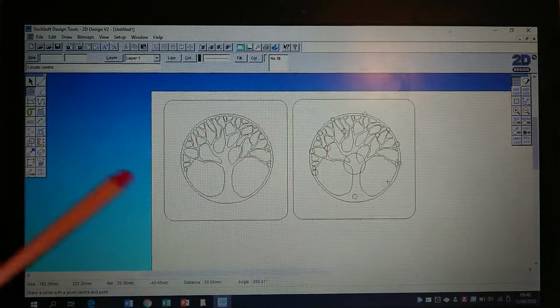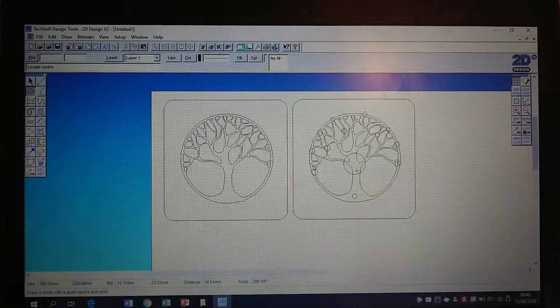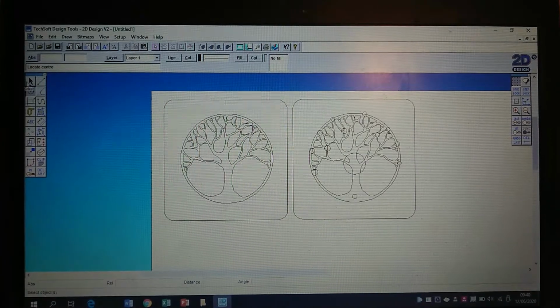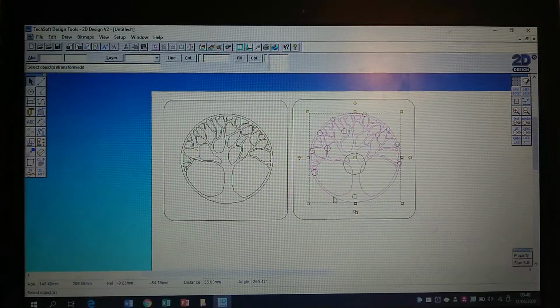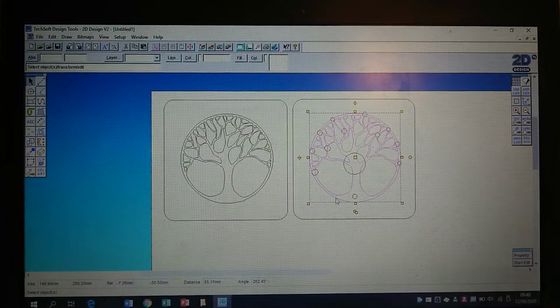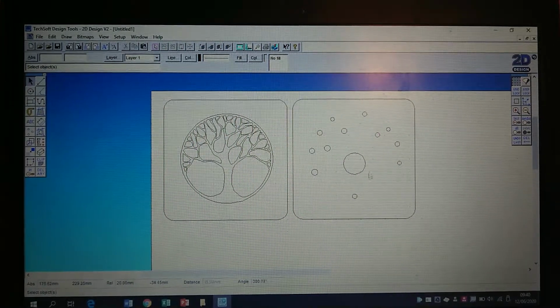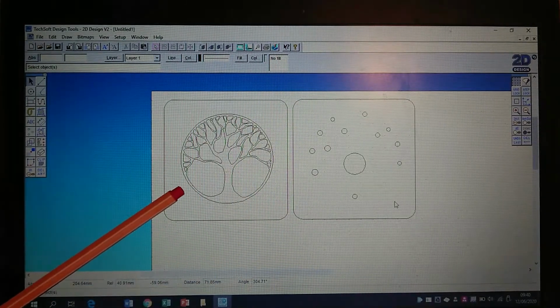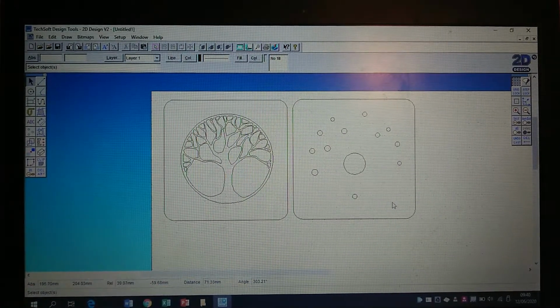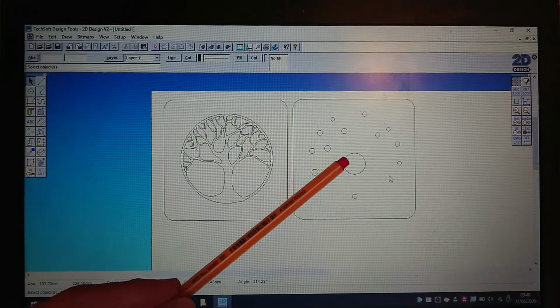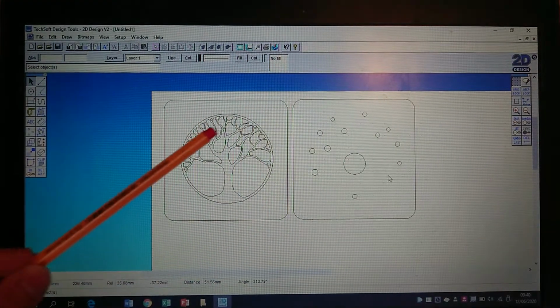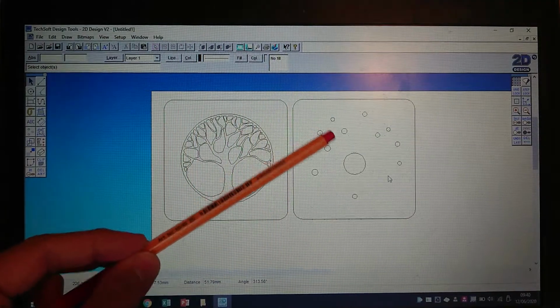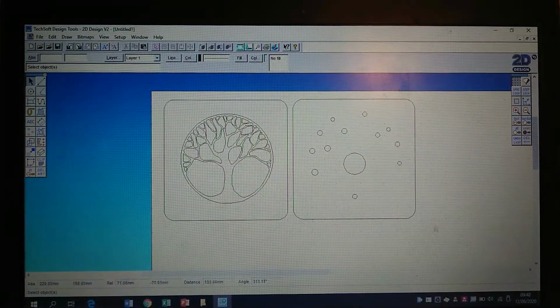Anyway, there we go. So I've got a filler, my risers, and now I go back to the select tool, click on that tree shape, the original one, and delete it. There we go, these two pieces here. I can then laser cut them. I can put this piece on top of this piece when they're laser cut, and they're two physical bits of wood. I pour the pewter in here, it fills up the mould, and the air comes out of these holes as it fills it up. That's the plan, which should work.